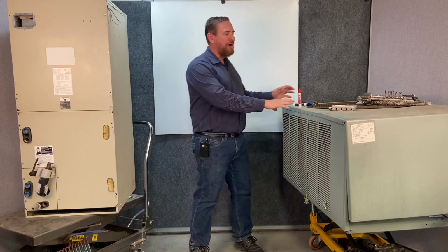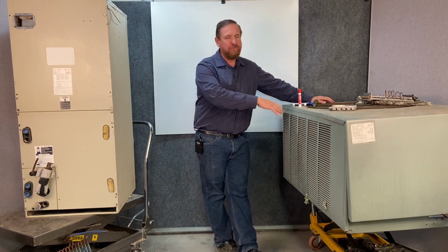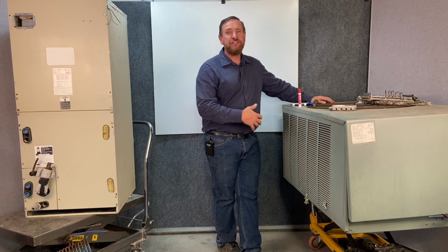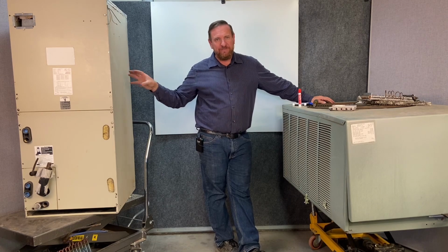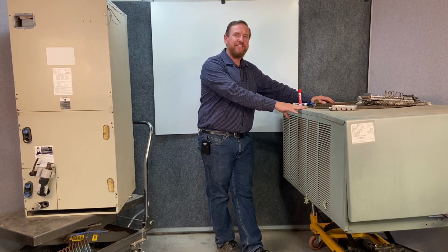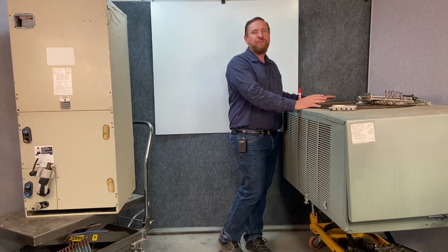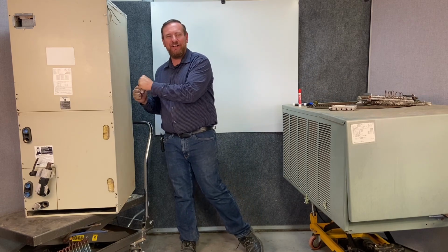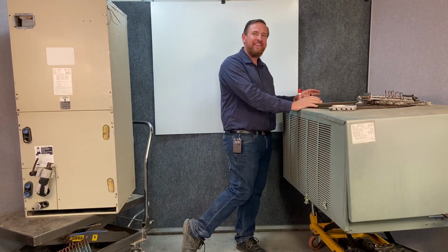And then here's going to be our outdoor unit. This unit's going to be located somewhere on the outside of the house, maybe even on the roof. Now, if we're talking refrigeration, it's going to be outside of a box. You'd have inside of a box and outside of a box, or refrigerator, inside of a box versus outside of a box. So this is going to be our outdoor unit for residential. This is where we're rejecting the heat. So we're absorbing the heat out of the house here and rejecting the heat out of the house here.